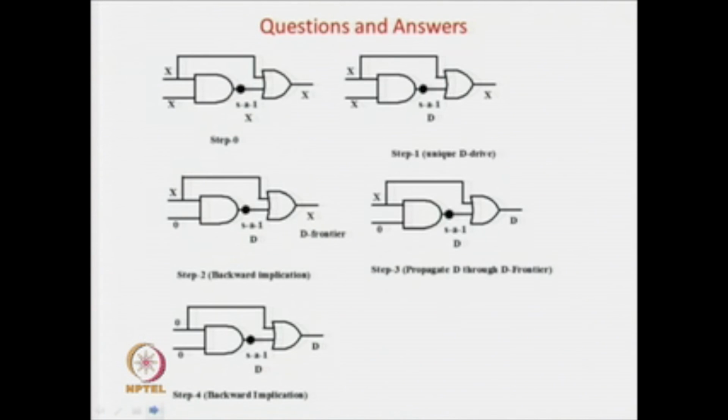Next example, last question actually. Explain using an example why singular cover is used for implication and not fixed value of signals, that is x0, 0x. Why do you want to keep so many x's in our circuit in DAlgorithm and not use any other stuff? What do you mean by any other stuff, like 1 1?